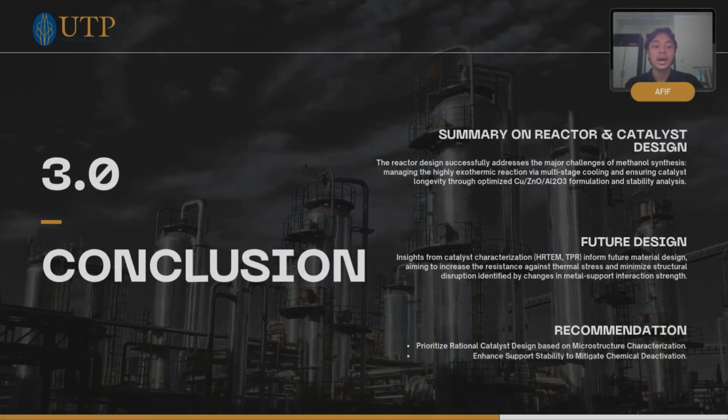To conclude, our reactor and catalyst design successfully manage the exothermic nature of methanol synthesis with multi-stage cooling, while the optimized catalyst formulation ensures long-term stability. Looking forward, insights from characterization techniques like HRTEM guide future material design. The goal is to increase resistance to thermal stress and minimize structural damage caused by changing metal-support interactions.